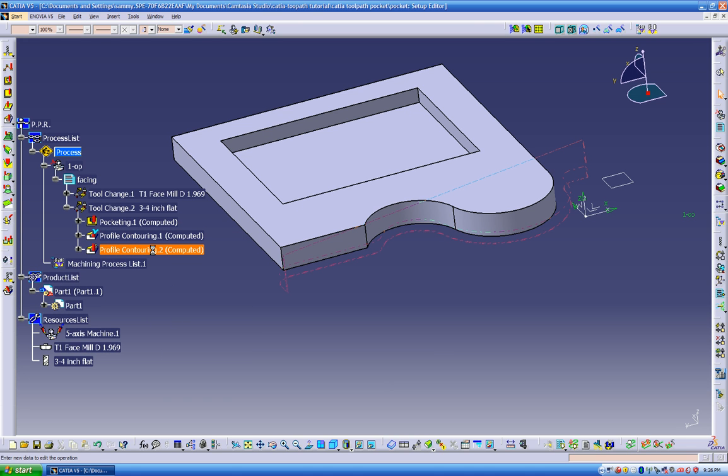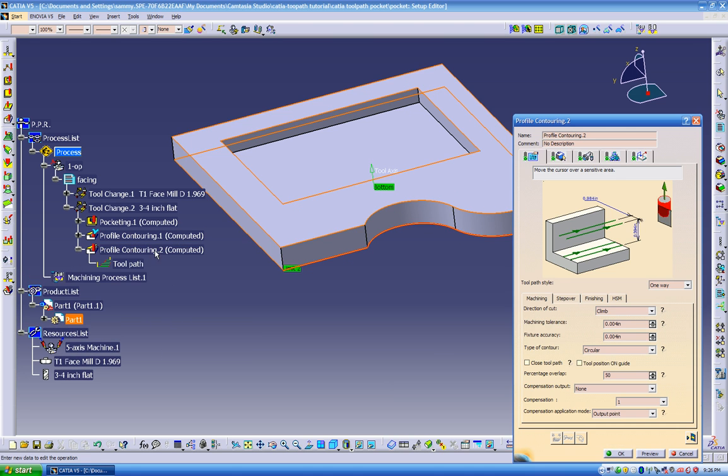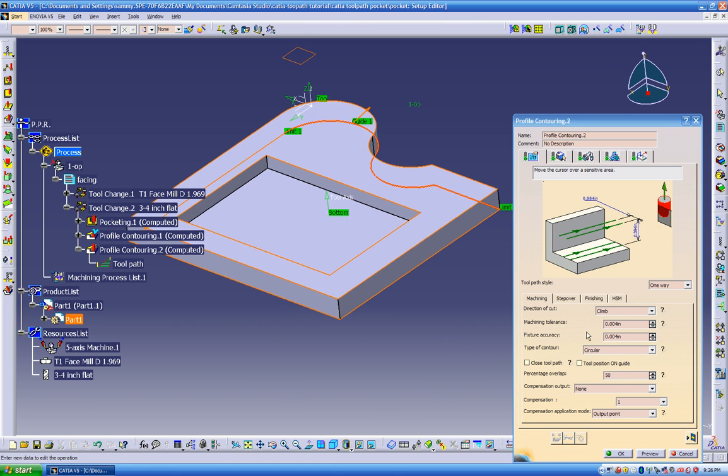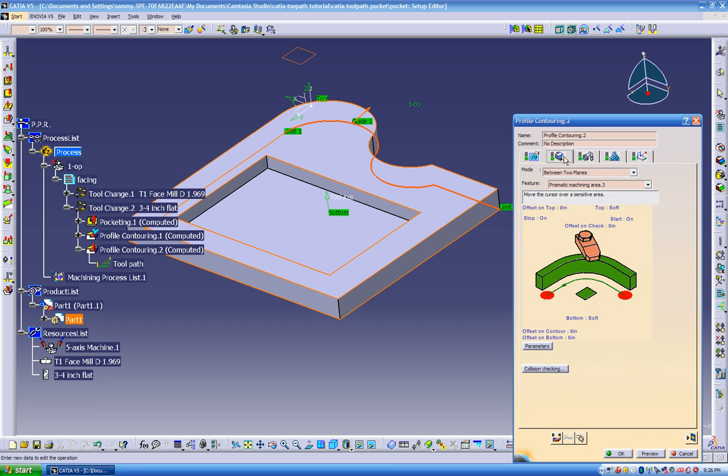Double click on the operation. And let's go to the back of the part. Leave all this the same. The only thing we're going to remove is going to be those endpoints and this profile. We're going to leave the top and bottom the same because it's the same part, the same level. So let's do a right click and let's go back to remove all contours. Same thing to the points. We're going to remove this.